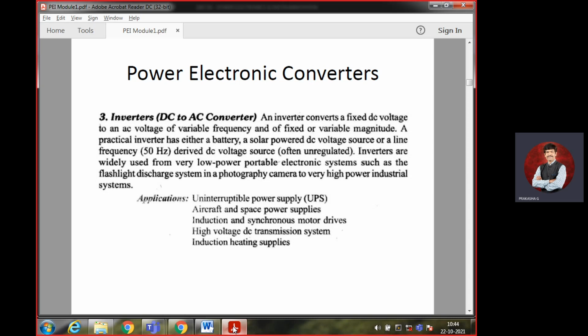At T3 to T4, I will be switching on this and this. Now what happens? The flow of the current is in a different direction. It comes in this direction, goes to BJT3, then goes in the opposite direction through BJT4. So here, negative to positive, the reverse direction is going to flow. Previously it was positive to negative, now it's in the reverse direction.